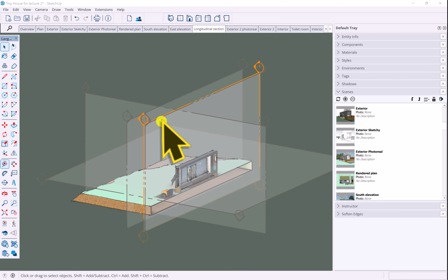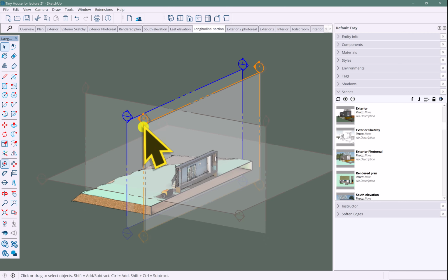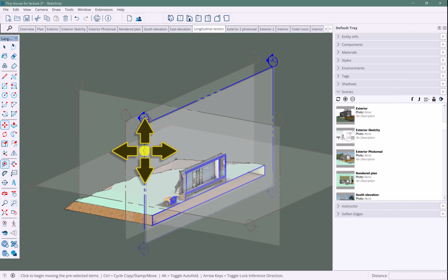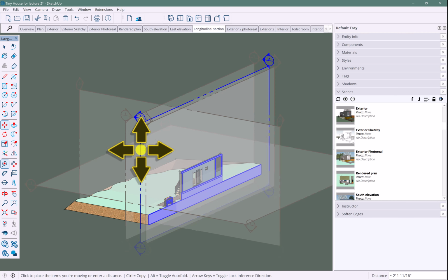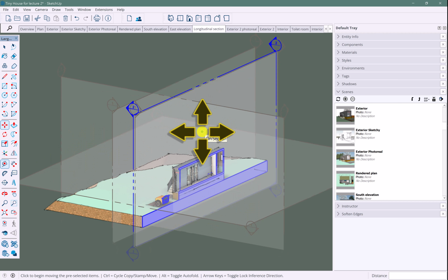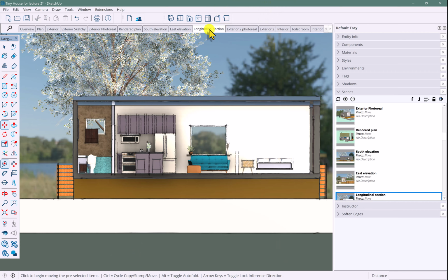And one quirky thing about the way SketchUp works is a section and an interior elevation, basically for our purposes, work exactly the same way. You insert a section plane here, and this orange one, I believe, is the one for my interior elevation. You just want to make sure when you draw it that you move that section plane. Typically with an interior elevation, you don't show any furniture, so the section cut, the actual section object, should be just off the wall, whereas a building section, let me switch to this longitudinal view, you typically do show a lot more of the interior.